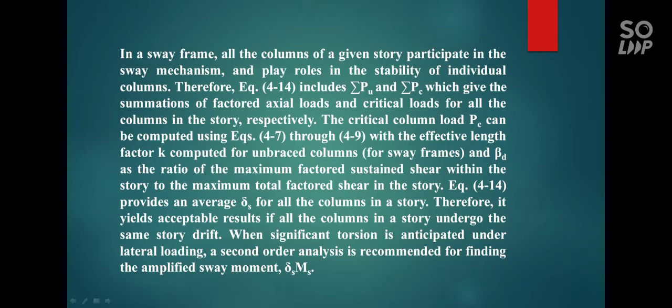Therefore, it is an acceptable result if all the columns in the story undergo the same story drift when significant torsion is anticipated under lateral loading. A second order analysis is recommended for finding the amplified moments.